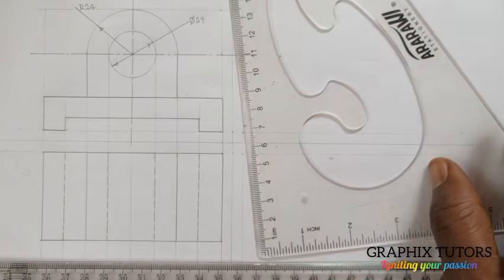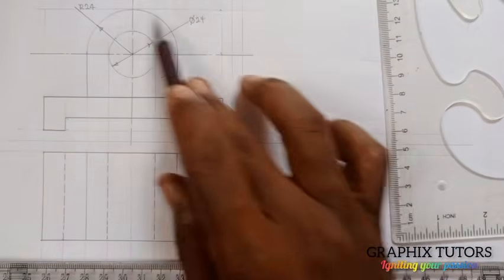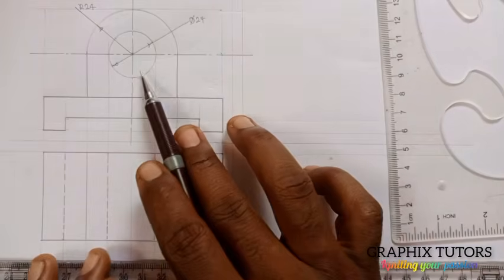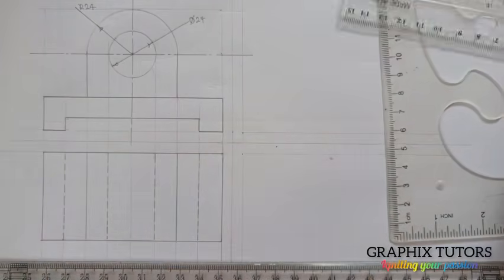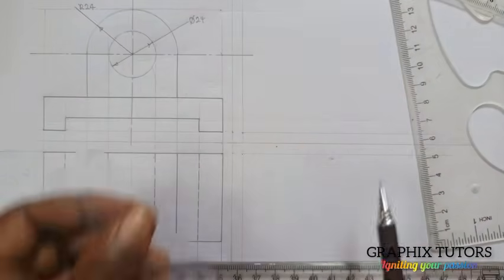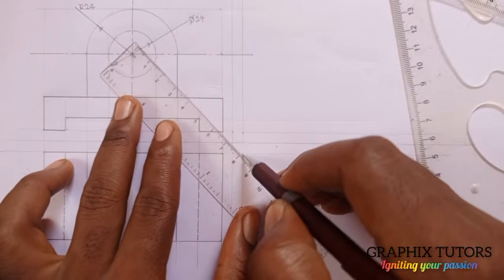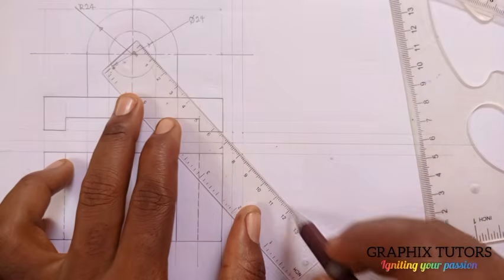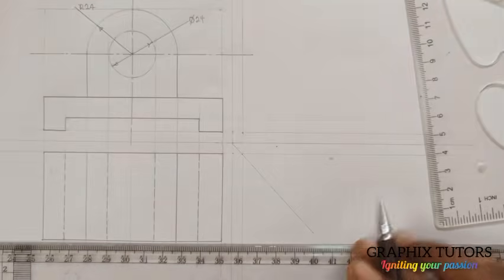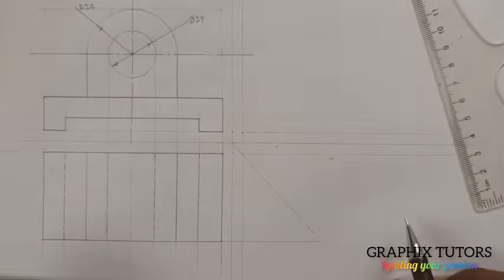Now the next thing we have to do is to bring out the end view, right? I told you the elevation is the center of attraction. Every other thing is connected to it, both the end view and the plan. So if I want to draw this to connect to this, I must draw my perpendicular, my 45-degree here. So I'll just connect here and here together, or I'll bisect it, but this is easier and faster. I'll just draw it this way. So I'll connect this to this point here. I'll connect it to that point.